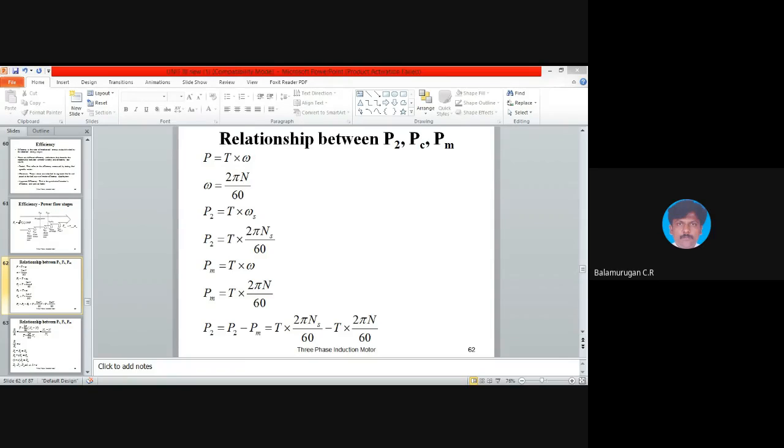So here, what the question asks is the equivalent circuit. You have to discuss anything related to the equivalent circuit. You can have a final equivalent circuit and explain it. Or you can have a first equivalent circuit, from that you can simplify that circuit and obtain the final equivalent circuit. Or you can explain the parameters referred to the primary or parameters referred to the secondary, and you have to write all the equations. Core loss component, what is I naught, what is IC, what is I mu, R naught, X naught, R1, X1, R2, X2, R naught 1, X naught 1, Z naught 1, Z naught 2, R naught 2, X naught 2. So you have to explain these parameters, then only you will get almost 6.5 or 6 marks.